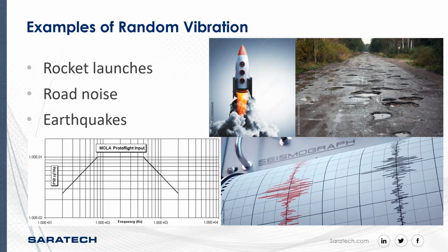As you can see here in our lower right-hand image, we've got a seismograph, and we've got our acceleration versus time. It's a very noisy input signal, and the time step size required to capture that sort of event would be very small for a very long duration, which will slow down our analysis significantly. Also, this is just a sample of a specific earthquake. Different earthquakes aren't always exactly the same sort of acceleration over time. So that's why statistical approaches are used for it.